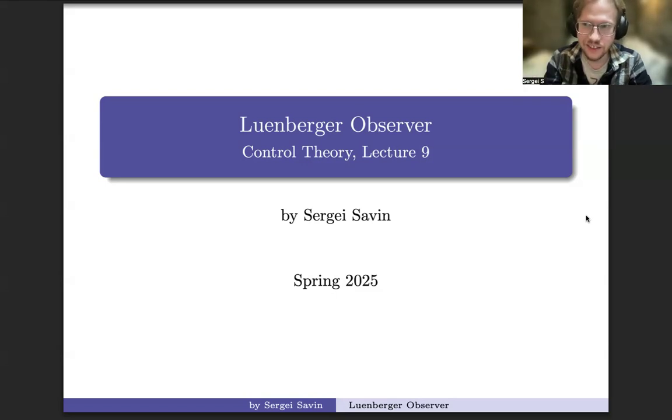Then in the last lecture, we managed to find what is optimal control. So the best possible control for a given cost function. We limited ourselves to quadratic cost function. That is why we got the linear quadratic regulator out of it. It is the best possible control for a given cost function. An alternative to pole placement, a very useful tool, right?